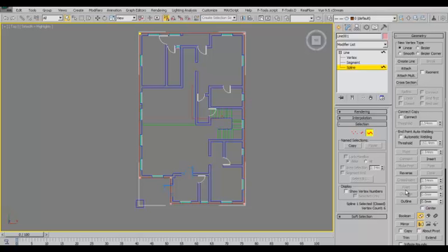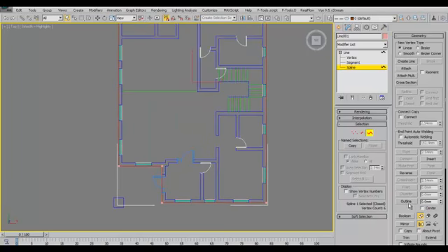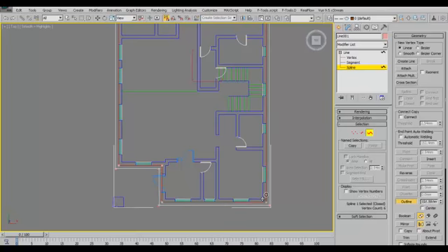Now under the geometry parameters, we choose outline. First I pick this outline to know exactly where it's going to offset to. Let's see what we're talking about. We can do it in real time by picking this, and you can input your data here. We want our walls to be 225 thick, so we pick the outline, then we check.